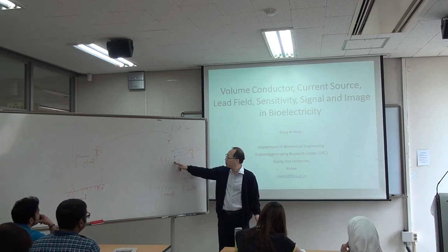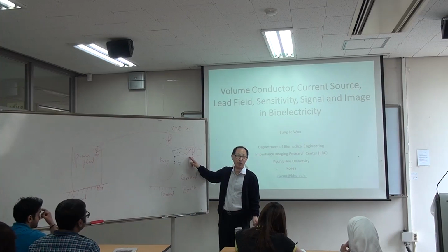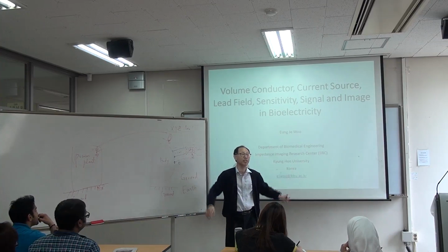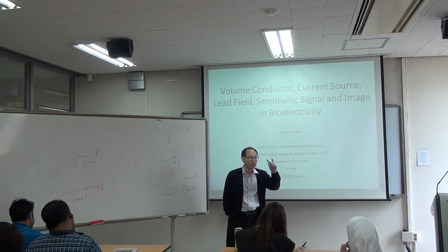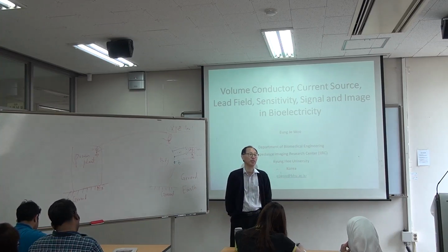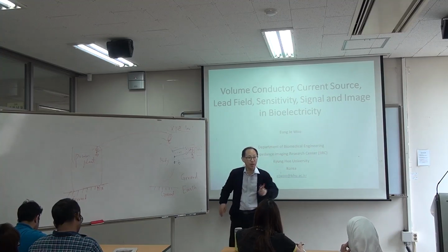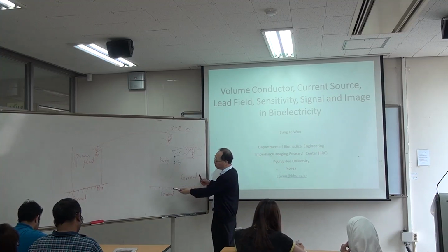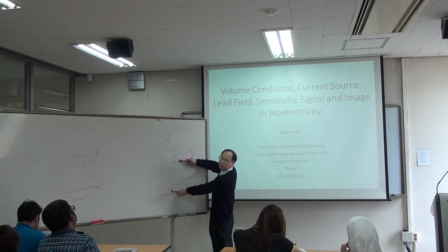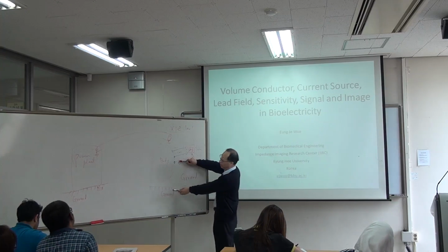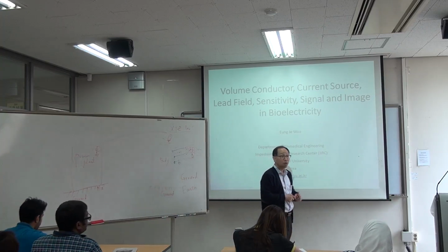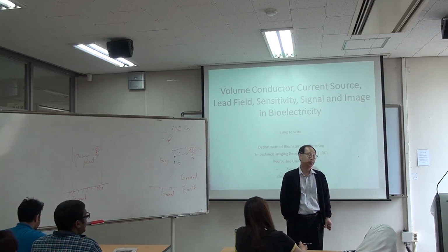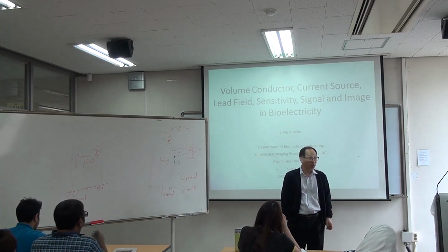Then this point and the circuit reference point are going to be at the same voltage reference, an equipotential surface, supposed to be 0 volt. But if you really measure the voltage between real ground and this circuit voltage reference point, then the voltage difference between these 2 points could be 100 volt. Who knows? Nobody knows.